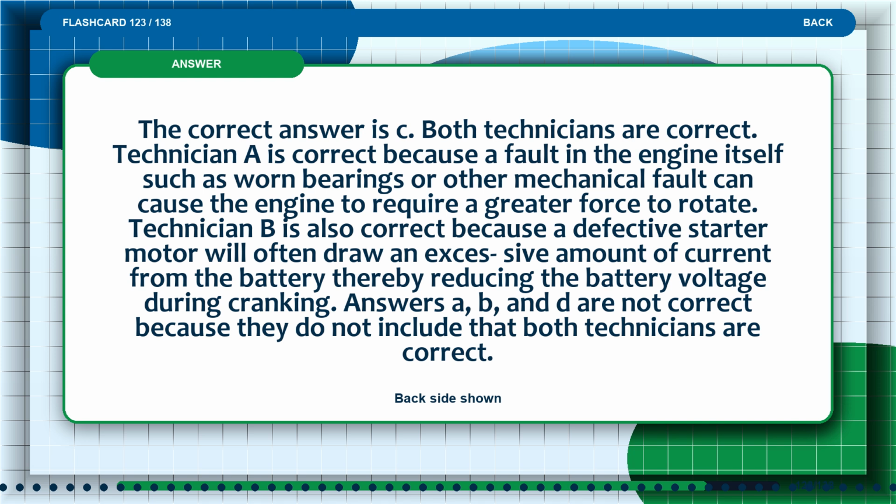Technician B is also correct because a defective starter motor will often draw an excessive amount of current from the battery, thereby reducing the battery voltage during cranking. Answers A, B, and D are not correct because they do not include that both technicians are correct.